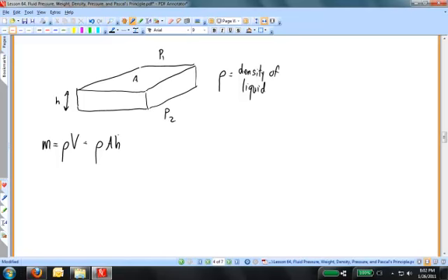There's pressure all around on all sides of the fluid, but the pressures on the vertical sides cancel each other out because they're in opposite directions if the fluid's in equilibrium. And now the fluid is in equilibrium, so the upward pressure must balance the downward pressure. So the upward forces must balance the downward forces. Well, now the weight of this fluid is equal to m times g.